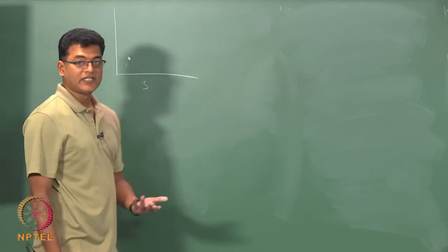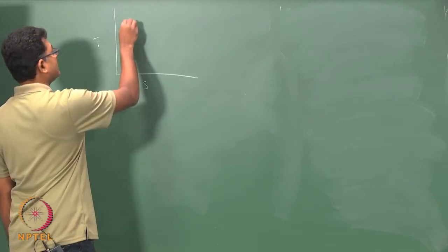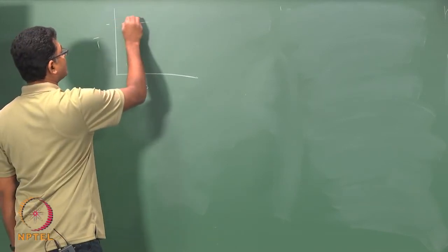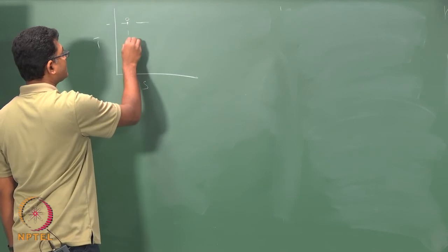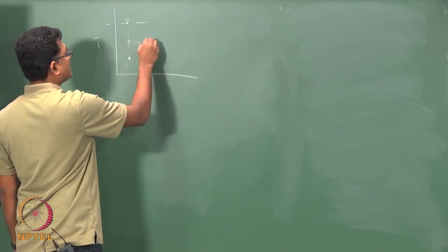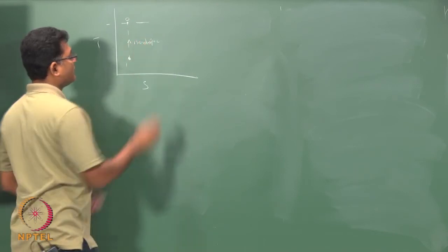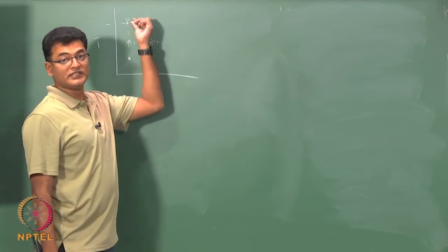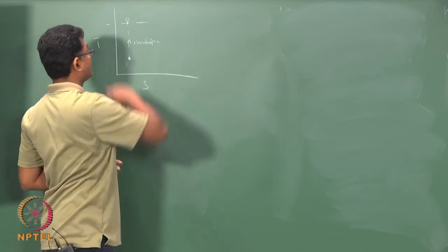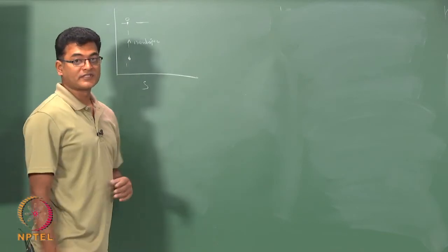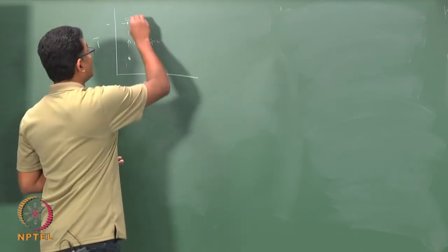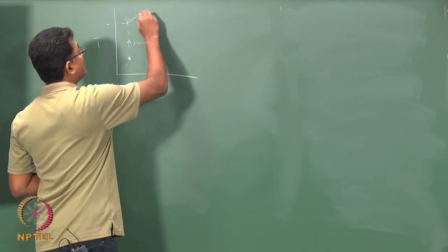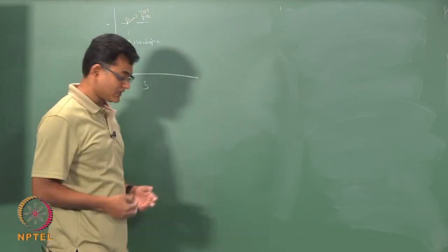For any given state, there is an associated stagnation state, which is reached by an isentropic process. So, you bring the velocity isentropically to an imaginary state where the velocity is 0, and you call that your stagnation point, and associated with that you have T01 and P01 and the other stagnation quantities.